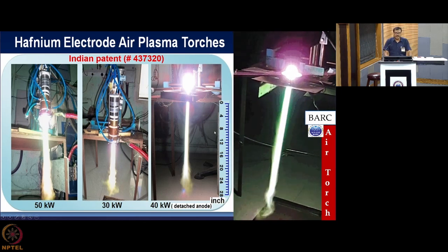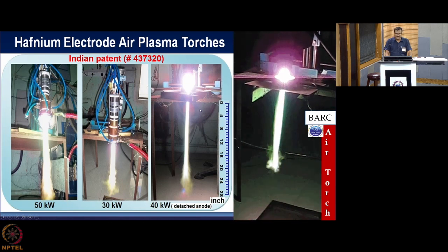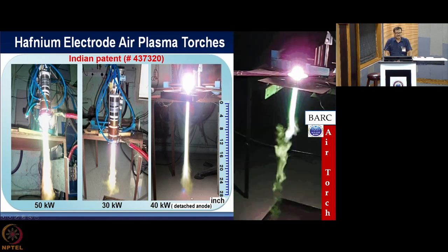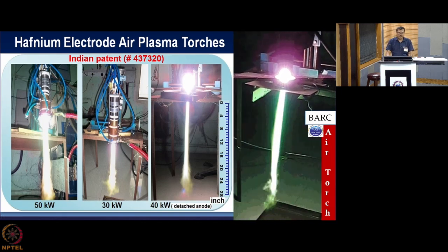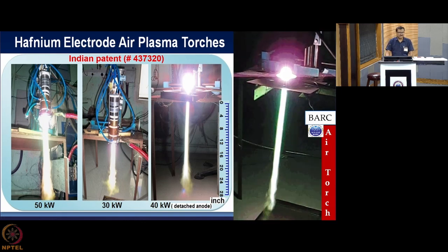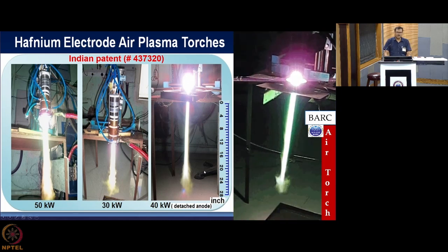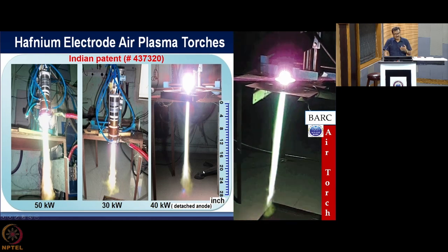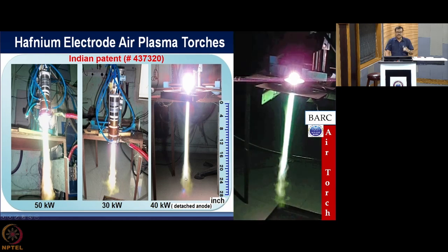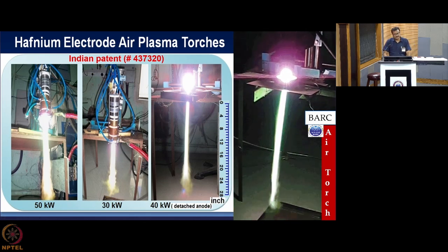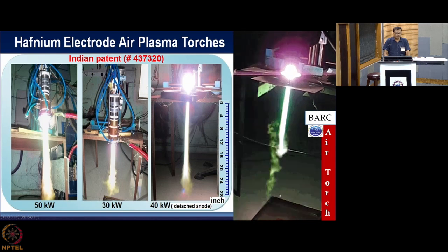So what benefit are you getting? You are getting length so high, and temperature also becomes high because of the constriction of the plasma jet. Now, when the length goes high, you know that a cylinder gives you a much larger volume, so you are getting a much better plasma volume over here. So your process zone increases, so process efficiency increases, and because of the higher temperature, you can use it for relevant applications.